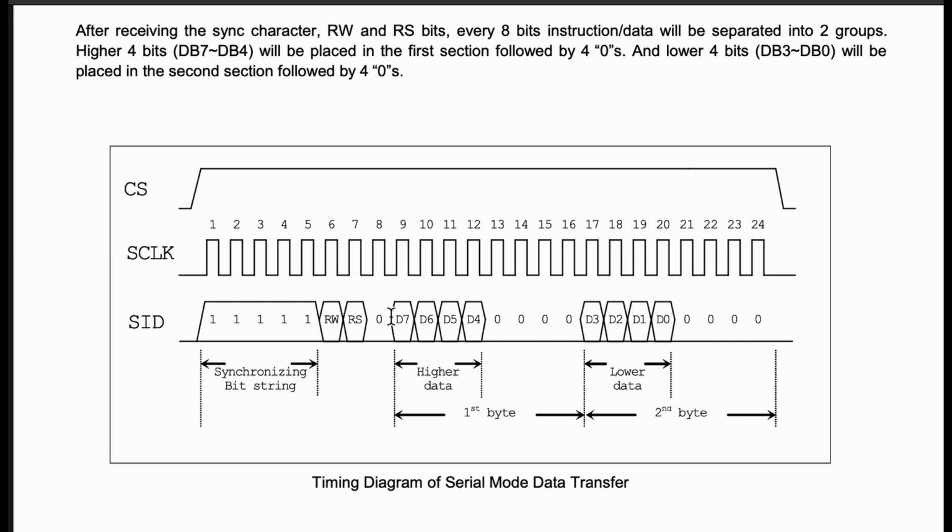And that's 1 byte. The next 2 bytes are the information that you would like to send, but split into 2, so essentially a 4-bit transfer. It doesn't say specifically here, but these bits are recognized when the clock is high. So let's now implement this protocol on the Z80.